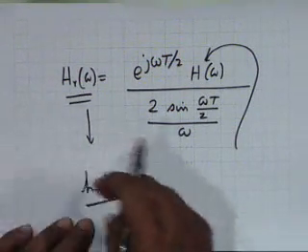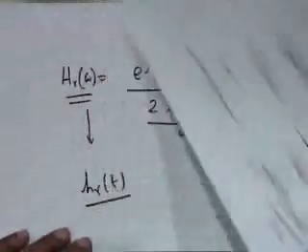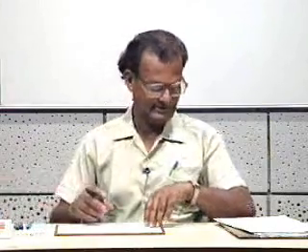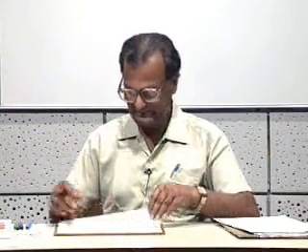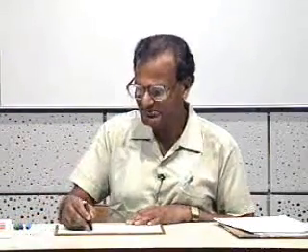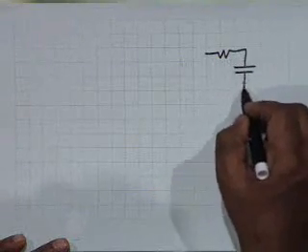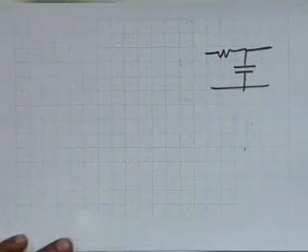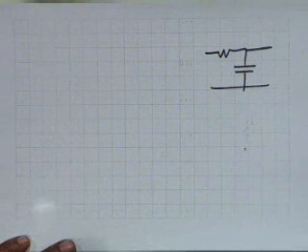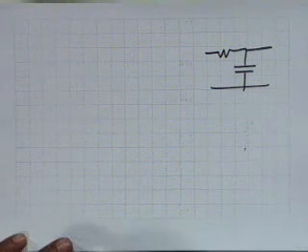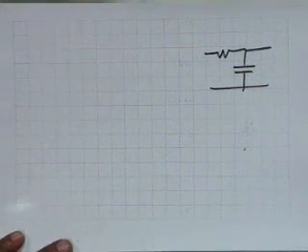Alright. However, good approximations to this can be obtained in practice, and we shall look at them later. Even a simple RC filter like this may do the job reasonably well, provided your frequency content is not too high.